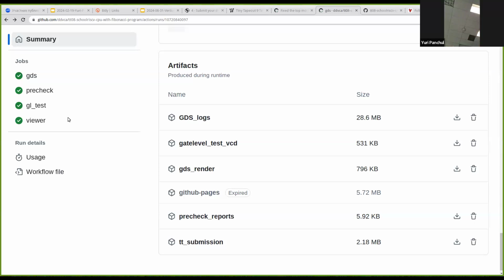Oh, this is SDF fast. I'm just looking for their reports. Okay, let's see, static timing analysis report. STA. Is there a target clock speed? This is not the target clock speed. We set the target clock speed. This just shows the critical path.